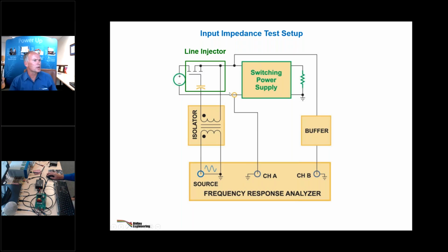Okay, so a couple more questions there. Heatsink inside: we take our FET, we mount it on a heat spreader, and then we slap it down to the aluminum case. So the whole case is the heatsink for the system. You can probably put 30 watts into this thing before it gets too hot to touch. So that's how we do the heat sinking there.